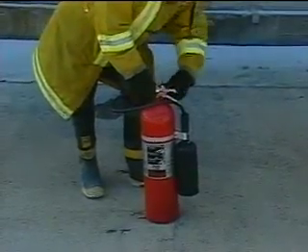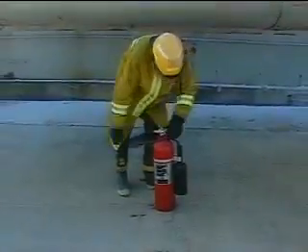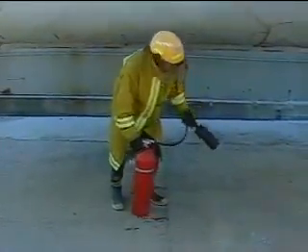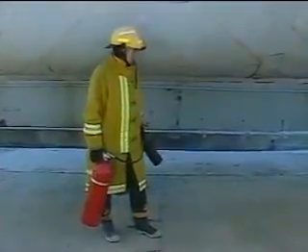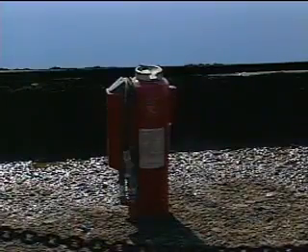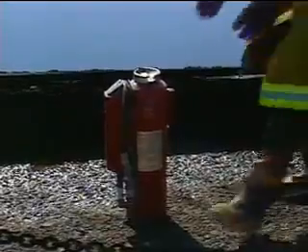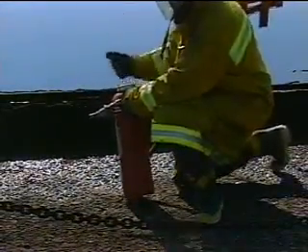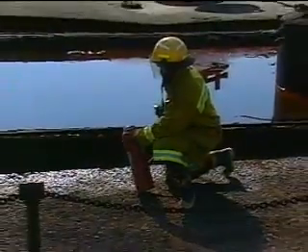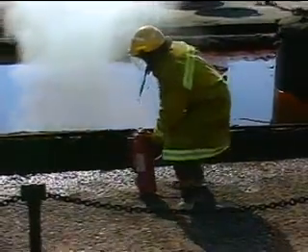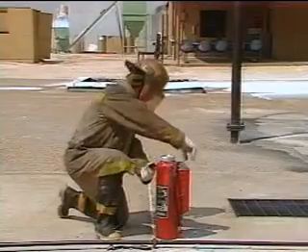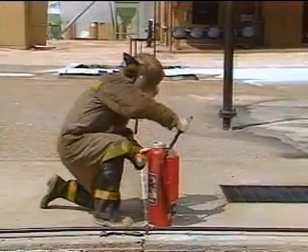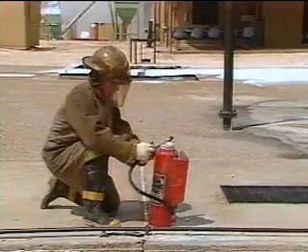Many extinguishers are operated by pulling a ring pin and squeezing a lever. Others may require you to remove the hose and pin. Some models require a hard rap against the top lever to become charged. Once the unit is charged, briefly test it to make sure it's working properly. Other units may require both removing the hose and physically charging the unit by hitting the top lever.